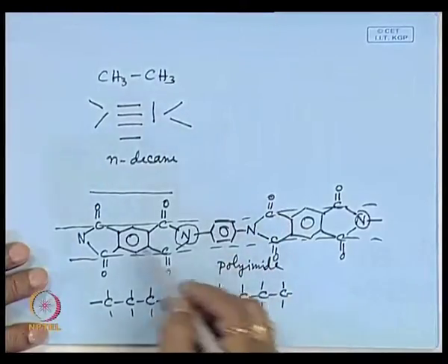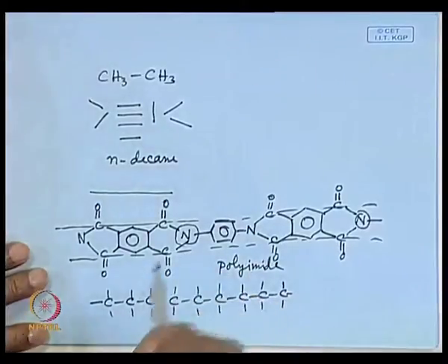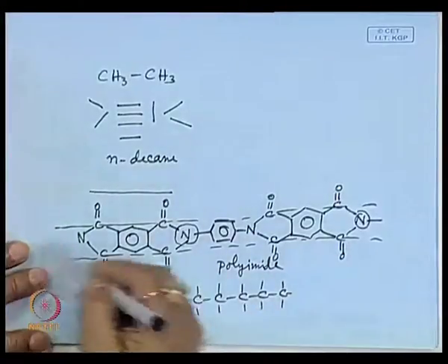So, molecules having such structures prefer to remain in an ordered condition even in the liquid phase. I mean in the molten state or in solution. You can put this polymer in a solvent and get a solution. In that solution it can remain in a rod shaped or ordered configuration, or in melt condition also it can maintain its rod shaped configuration. We can say that it is a liquid crystalline behavior, liquid crystalline structure of the polymer.